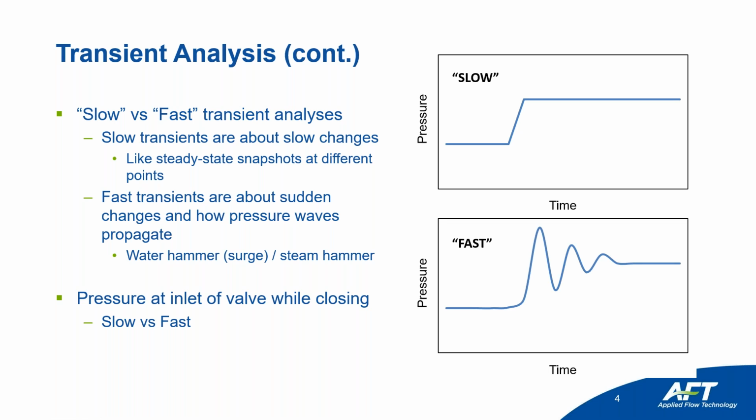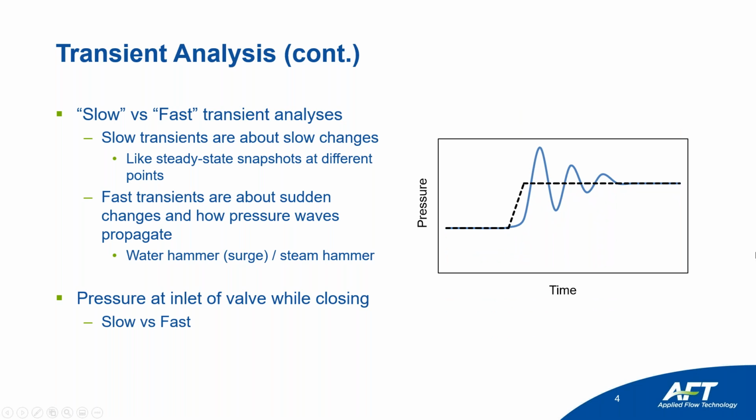That same valve closure, though, we can look at through the lens of fast analysis. In reality, the closing of the valve is going to cause pressure spikes and waves to propagate. It's not just a different set point. It has effects during the change. If you look at the two, sure, they start and end in the same place: they start at a steady state and end at a different steady state. But what happens in between is vastly different. And xStream is going to model these fast changes with things like valve closure or relief valves, all of the things we talked about. Any transient event is going to have wave propagation, and we want to check that out and see the magnitudes, check the forces, and see which relief valve is going to go off first, things like that.